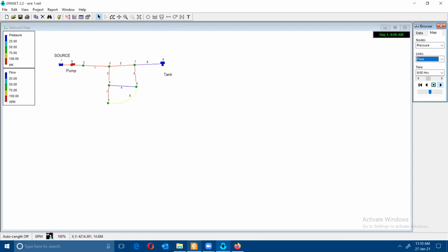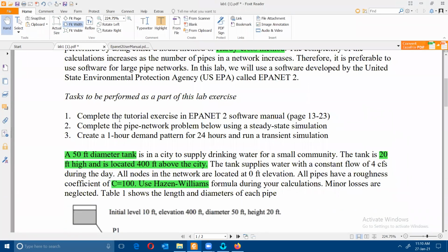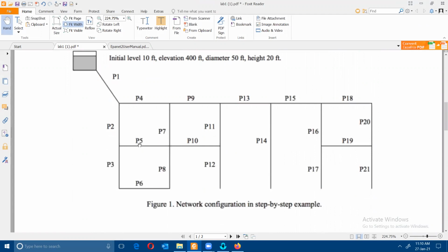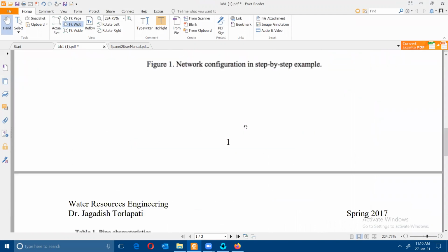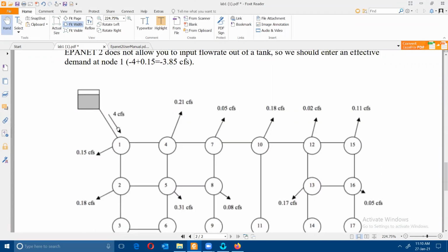And once again, what you have to do is create yourself one of these networks. Just a reminder that for the initial level in this pipe network, there is a difference with the tutorial: here you will have to put the base demands in the nodes.